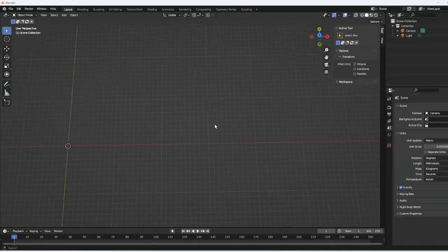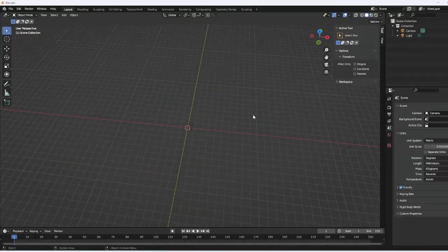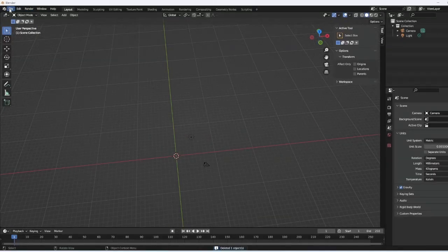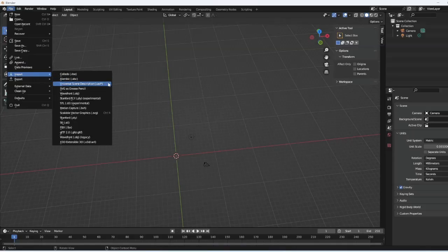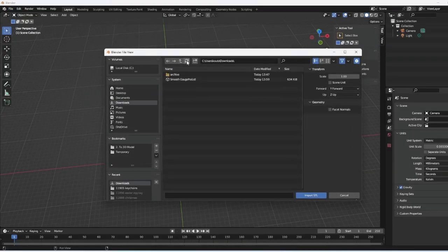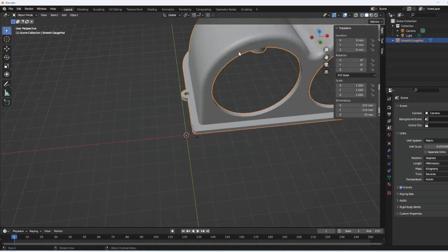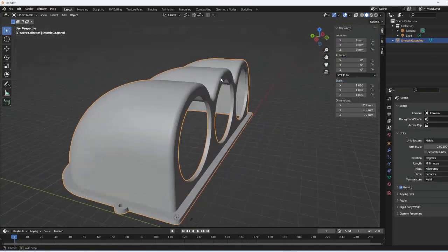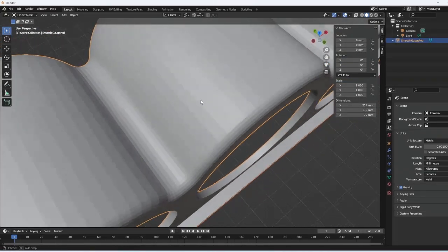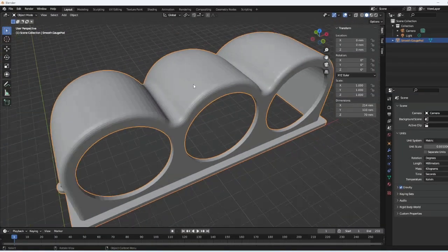And if you open up Blender, you'll see this kind of thing here. We're going to import our part and check if we've got enough detail. So go File, Import STL. Now I'm going to see it there. Bang, open that. All right, and I'm just going to zoom out so we have a look at it. You can see that's quite smooth, but we can see these triangles already. That's a bad sign because we're still in object mode, which smooths all that out.